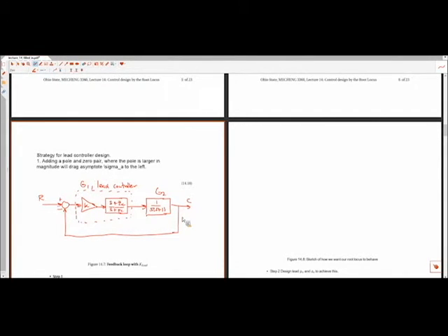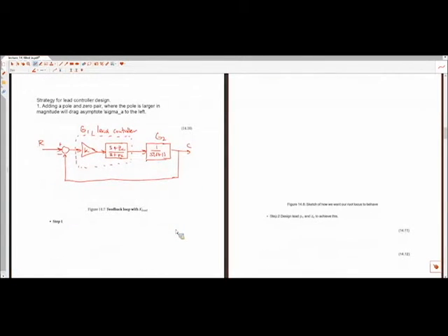And then if we want to put this in the context of how we always look at the root locus plot, we say, all right, there's a single term k that we're going to vary from 0 to infinity, and everything that has dynamics associated, we're going to lump into a single term g. I'll get to step 1 in a second because I ran myself out of space.